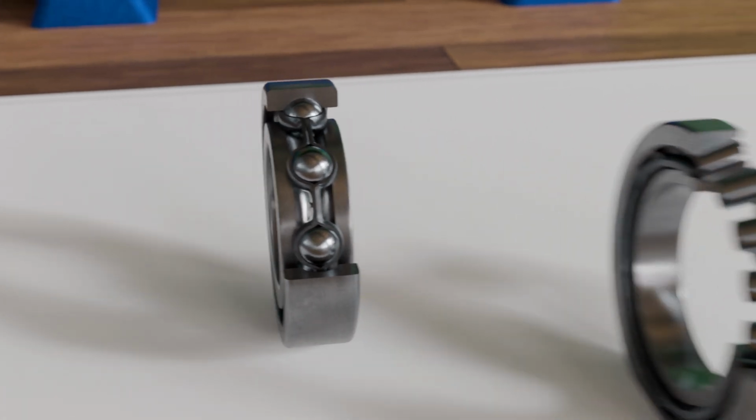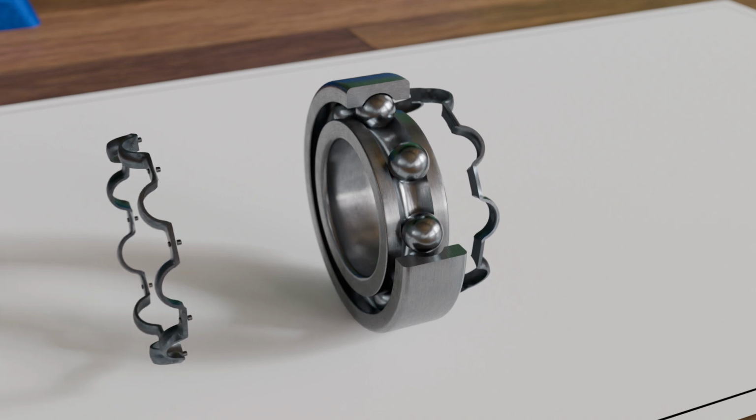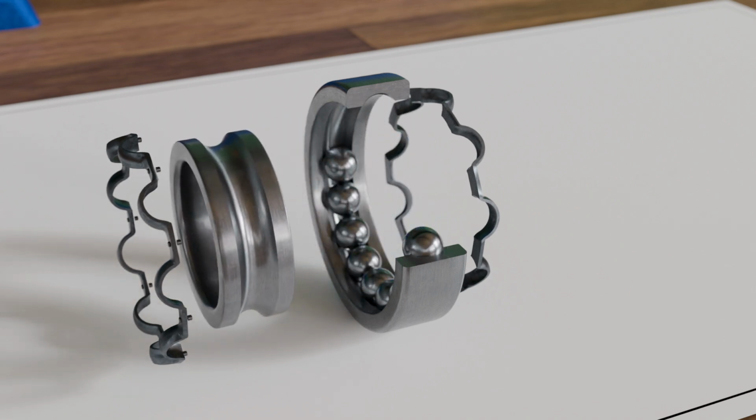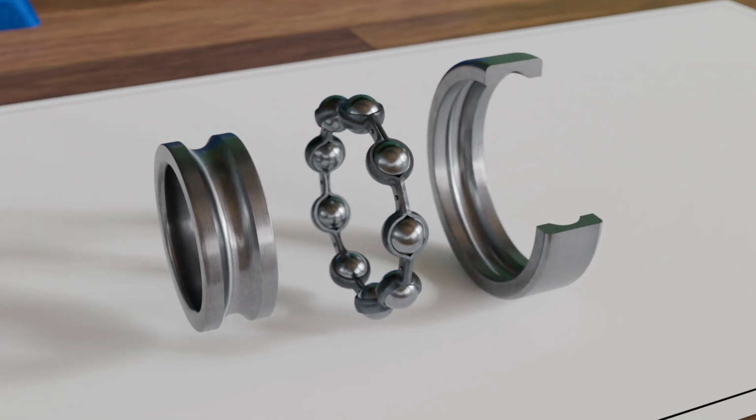Let us now take a closer look at the structure of a rolling bearing using the example of a ball bearing. As the name suggests, balls are used as rolling elements in this type of bearing. To prevent the rolling elements from touching or jamming each other, they are guided and spaced by a so-called cage. The cage ensures an even distribution of the rolling elements and thus a smooth and consistent operation of the bearing. Depending on the application, the cage is made of pressed sheet steel, aluminum alloys, or glass fiber reinforced plastic. In particularly large or heavily loaded bearings, solid cages made of brass are also used. Only very low sliding friction occurs between the cage and the rolling elements.